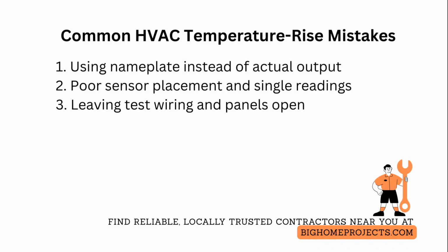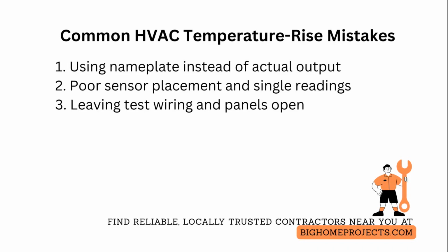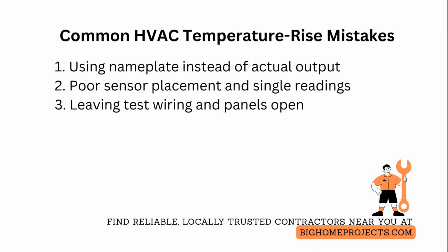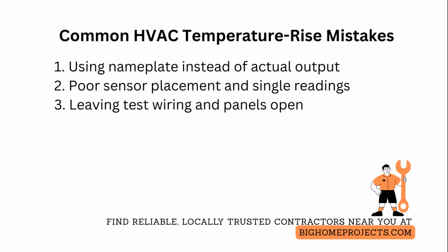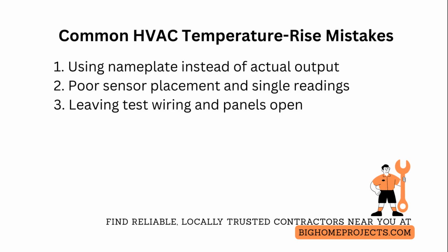One of the most common mistakes is using nameplate heat input instead of actual heat output when calculating airflow CFM, which produces inflated or deflated CFM values. Fix this by measuring combustion efficiency with a flue gas analyzer or by using manufacturer performance tables and applying the correct efficiency factor.